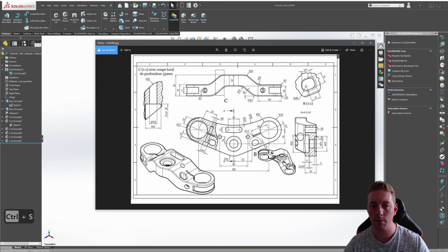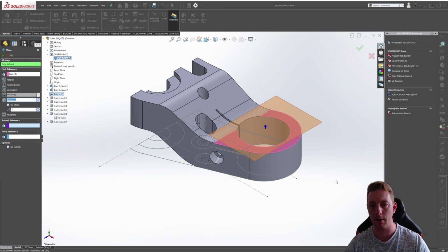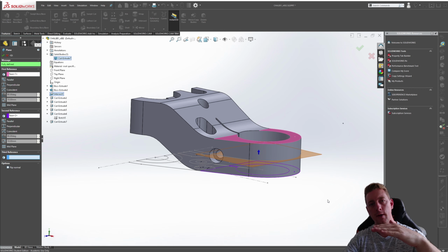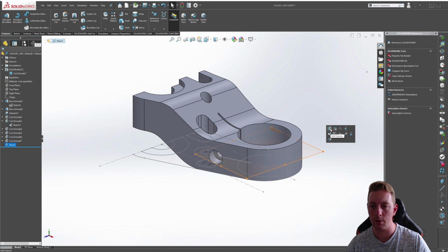The final piece we need to make is this cutout that goes around the center. So this one we actually need to create a new plane, and I find it's probably easier just to do a circle, offset it a little bit, and cut it through the mid plane. So we're going to create a plane using our reference geometry. We'll pick the top and this side, and if you pick two faces, it's going to put the new plane directly in the middle of those two. So we now have a plane right in the middle. We can click on it, go to Sketch.